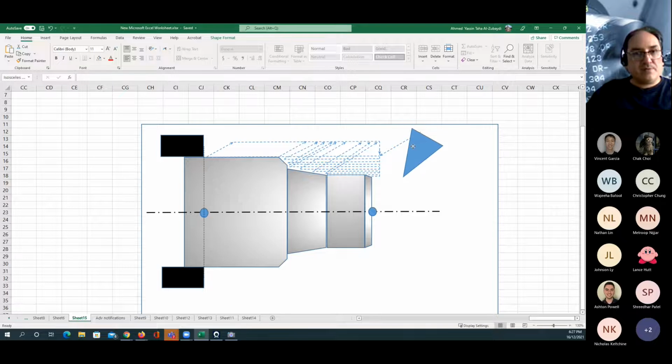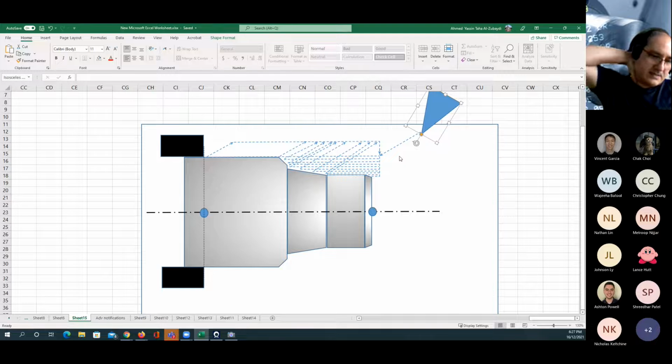Now, the depth of the cut here, as we mentioned earlier, will depend on the cutting tool material and the material we cut. And it's usually wiser, if you would like to have a good surface finish, to use less depth of the cut each time. But the problem we're going to have here is that this will take the cutting time to be longer than what we want to have.